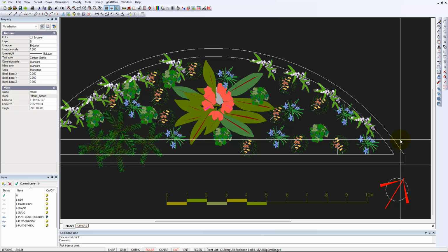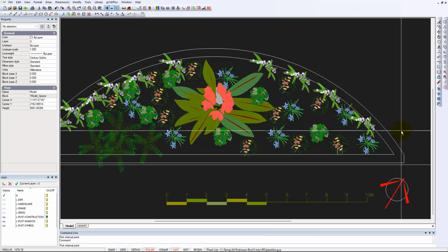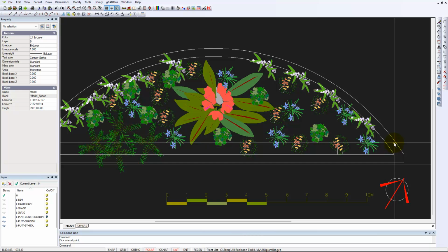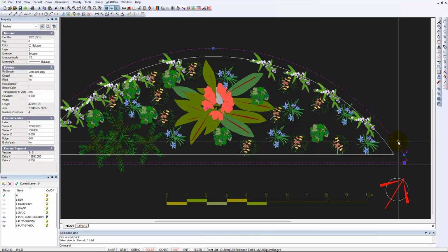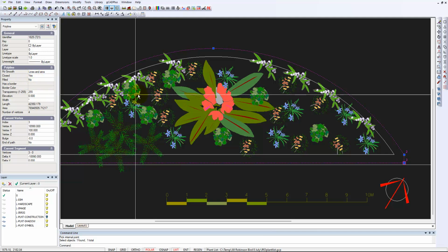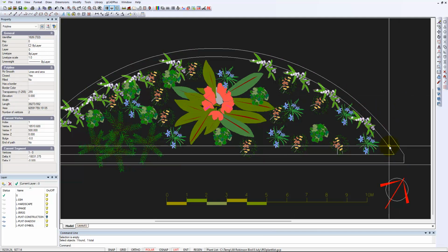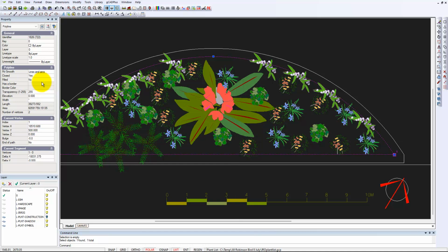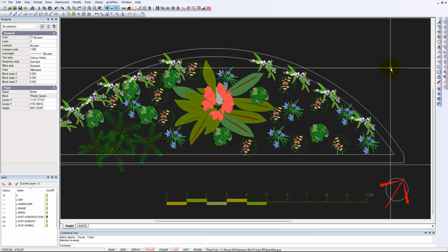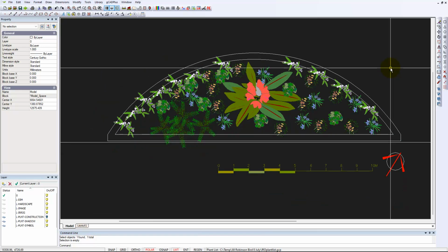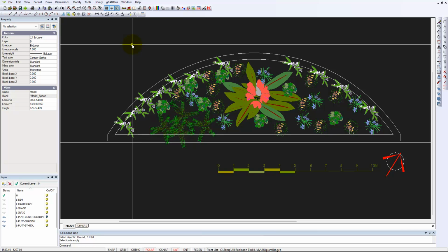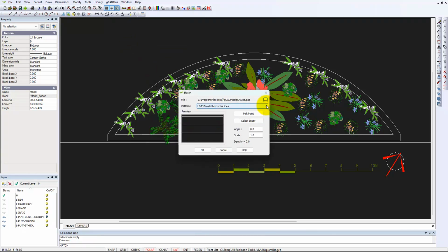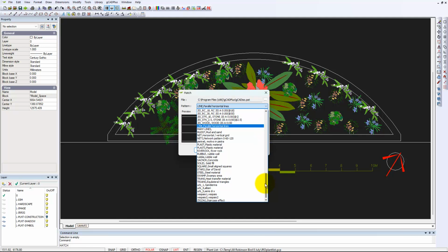And again, it should happen instantly, and it's not. So I'll escape again from there. And I'm checking over here that we've got a closed entity there and a closed entity there. So our hatching is not working well. It should find that area. I'll try again, and I'll just use a solid hatch, see if it can find the area.